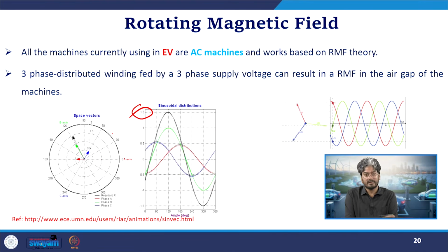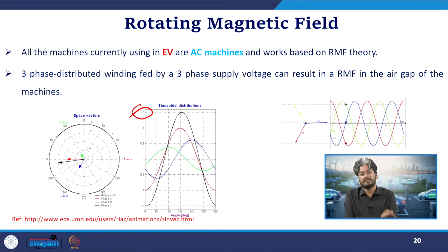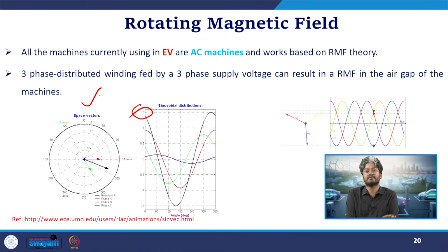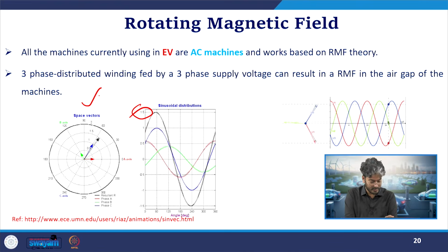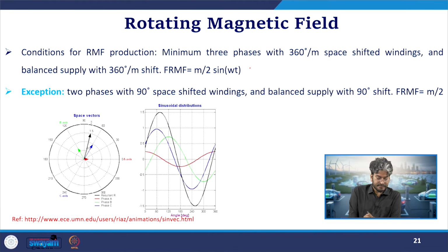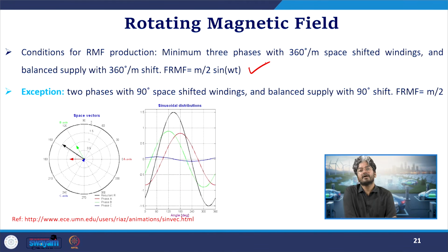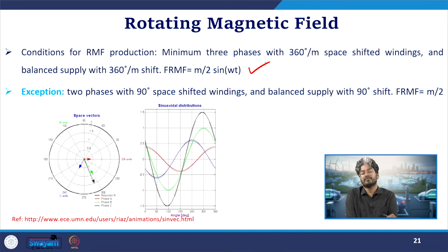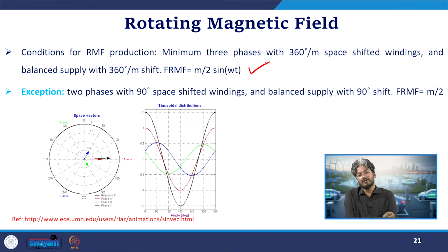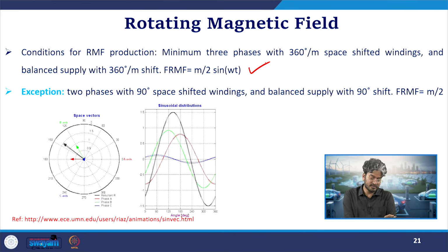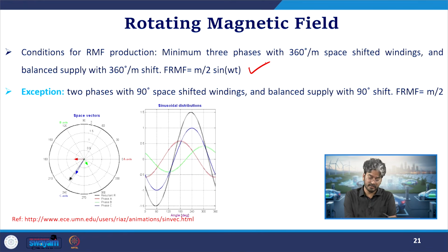Okay. So the concept of this rotating magnetic field was first established in our electric motors, then it was adapted for DQ frame control of the inverter circuit. Now, the condition required for production of our rotating magnetic field. The 3-phase structure is the most popular one. We can have 5-phase, 7-phase or a higher number of phases. In that case also we can have rotating magnetic field production.